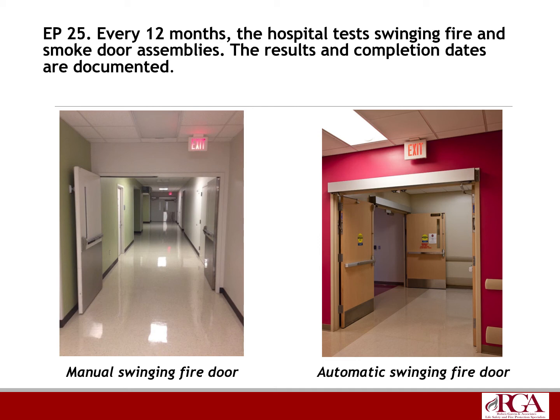Now, there's some debate about whether smoke doors need to be tested or not, but the fact of the matter is your smoke doors are just as important as your fire doors. And frankly, most of your smoke doors are actual labeled fire rated doors, whether they're 20-minute doors or 45. So just to make it easy, check all your fire and smoke doors. There's some controversy on whether or not the standard says you need to check your smoke doors.